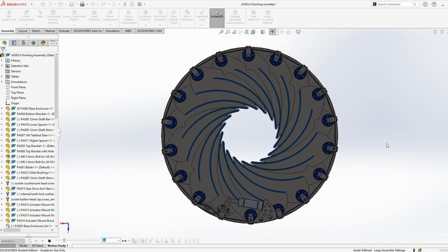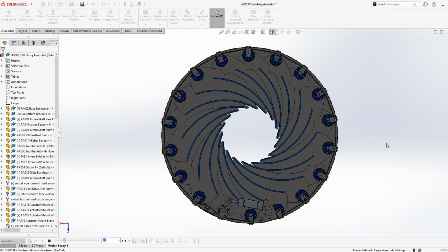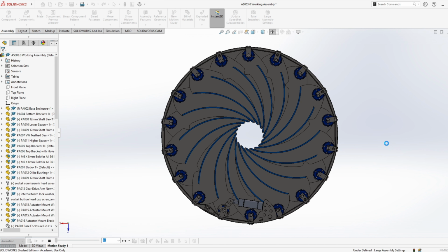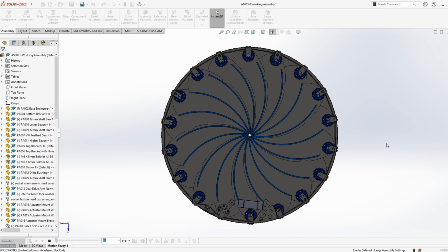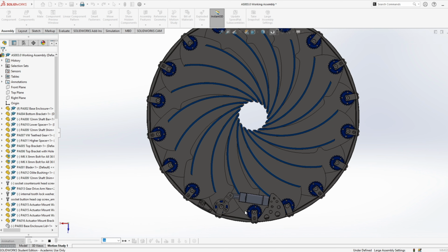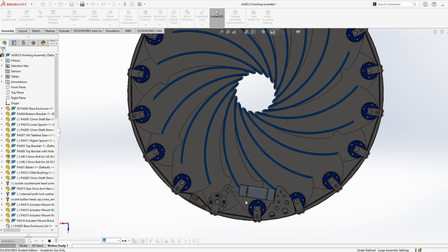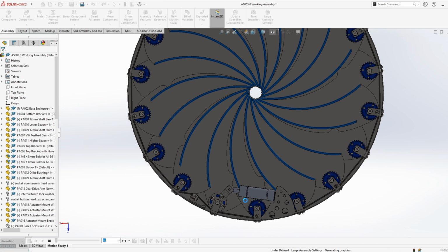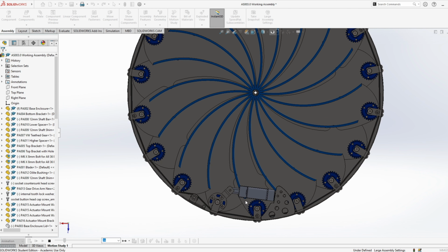As demonstrated throughout, there never appeared to be any issues with Prototype 1 during all the motion studies seen throughout the detailed discussions. However, major flaws occurred during the initial testing of Prototype 1. When this actuator, seen at the bottom of the diaphragm here, was powered up, controlling one of the gears seen here, the other 17 gears became out of sync with the one being directly driven by the actuator.